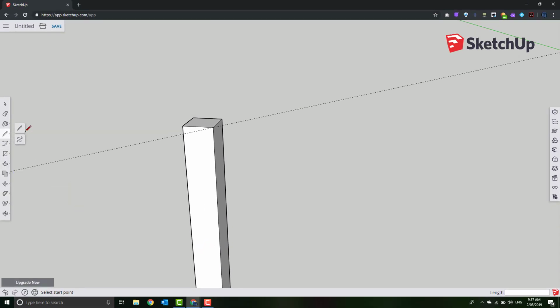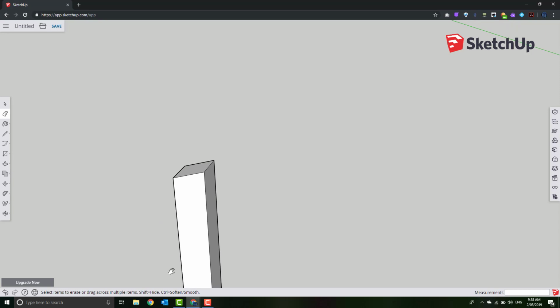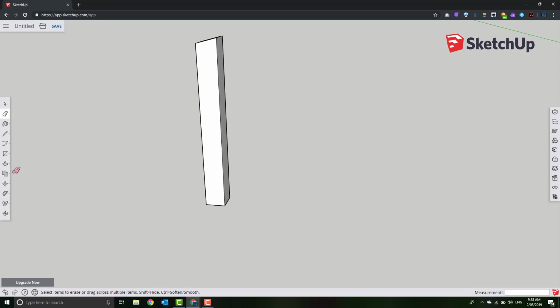I'm going to take my pencil, like we did in class, and I'm going to draw from the intersection. I've now got an intersection where my line here cuts this line. I'm going to click on there to my corner, and I'm going to push pull through. Then I'm going to delete the construction line. We're going to do the same thing with the bottom protractor, but this time we're going to go from this corner, same face, along that edge, and point it up, and type in 15.